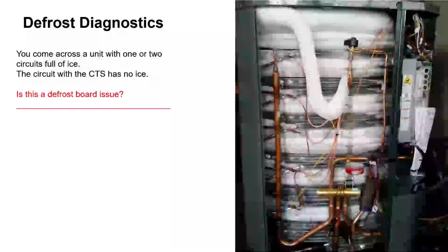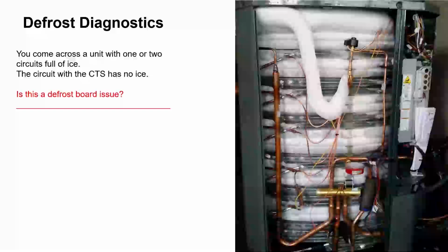All right, so let's jump a little more into the defrost diagnostics, starting with the fun. Some of you may have seen a unit like this. This is what we call banding. Unit has gone through defrost. Matter of fact, this one probably just barely finished defrost, and it looks like this. It did not complete defrost.